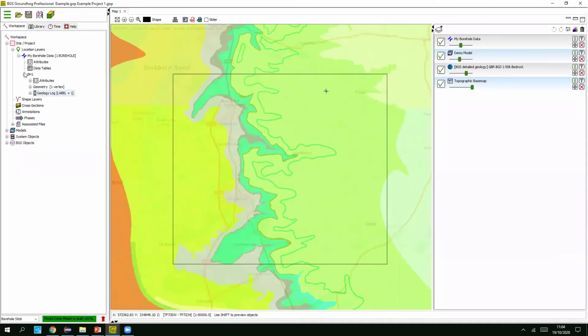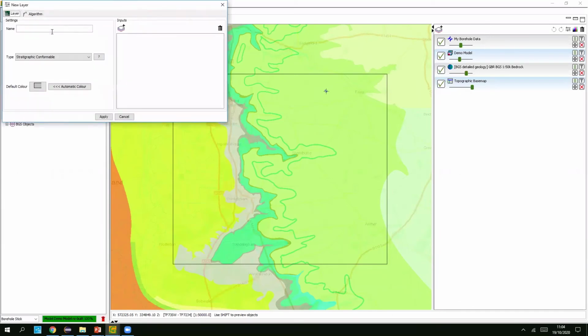So I'm going to rebuild those model layers just from that borehole information and see what happens. So let's add back in the Carlstone Formation. Pick a color. And then I'm going to grab, so now because we've got some data loaded, borehole data is an option as the import here. So this list slowly builds up as you add mapping, cross sections, etc. Borehole data. Click OK. Because it's detected it's a borehole, I then need to map because I might have multiple fields within that borehole data set. I need to tell Groundhog which folder and which field to use for the geology.